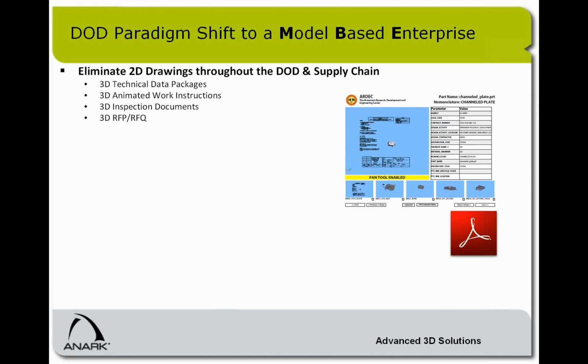Let me just describe a few terms. When we talk about model-based definition, at least in this conference call, that will be everything you do in SolidWorks to design your parts, design your assemblies, to put in your engineering custom properties, and maybe most importantly, you will be doing 3D dimensioning and tolerancing, GD&T tolerancing, plus minus tolerancing in a 3D environment in SolidWorks, which Paul will show you, as opposed to creating 2D drawings. So, if you will, the complete product definition is built in a 3D environment.